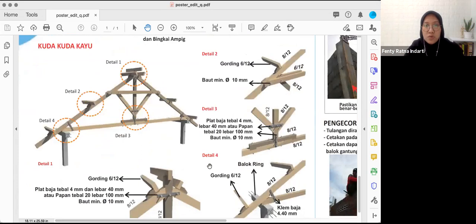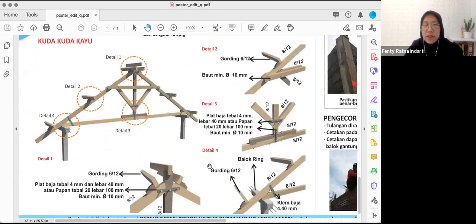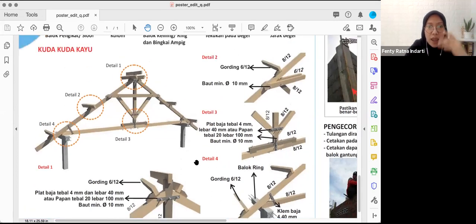Next, after that, you see the rafter here. Again, the rafter itself, if we are talking about roof structure, in European countries they only use rafters, battens, and hips, maybe valleys if the roof is connected like a valley. But in Indonesia, there are several parts like this one, and then there are additional layers so that you can hold on for the roof sheeting.